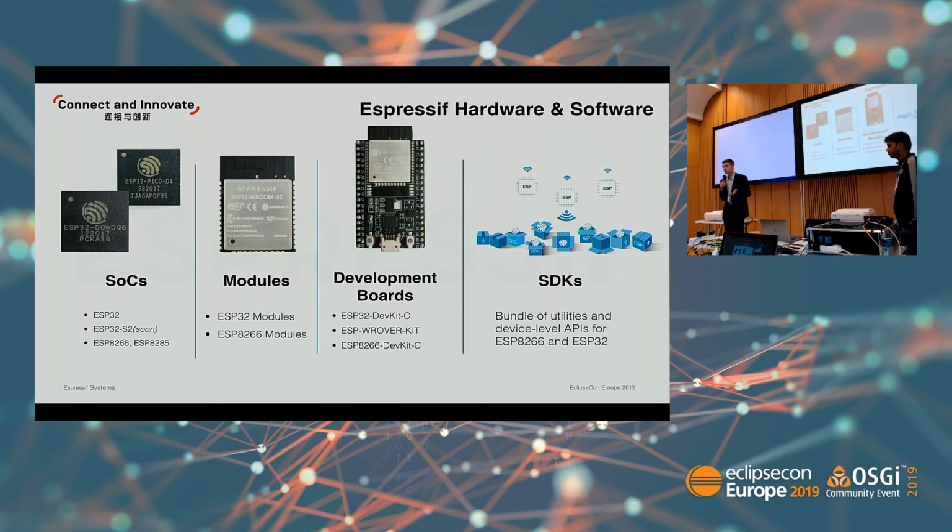We call them SoCs because they are slightly more complicated in terms of their internal structure than a typical microcontroller. So aside from being a microcontroller, what is a microcontroller basically? It does have some CPU, it does have some memory, it does have some peripherals typically used to control or interact with the external devices. So SoCs also integrate other things. Like in our case, they integrate analog parts, so there is Wi-Fi radio or Bluetooth radio. There are some ADCs, DACs, and so on.